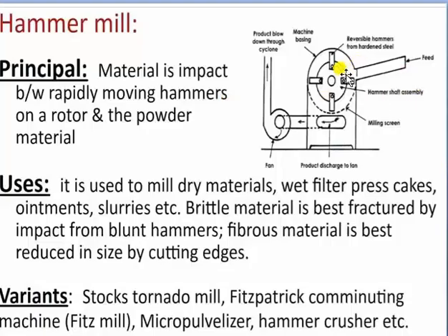Here, the sample feed will inlet. This vessel consists of the fixed hammer upon which, due to this machine, the vessel is moved. The hammer is also moved due to the impact force. The samples will hit the hammer and break down, and here your sample will be collected.